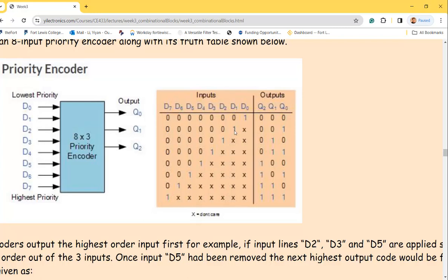If this one is getting flipped, and you don't really care about this one, then just don't cover it. You don't write that D0 into the logic expression, and that one equals your expected results. In that case, you don't have to list all the possibilities, just put a don't care over here. It actually covers all the cases.